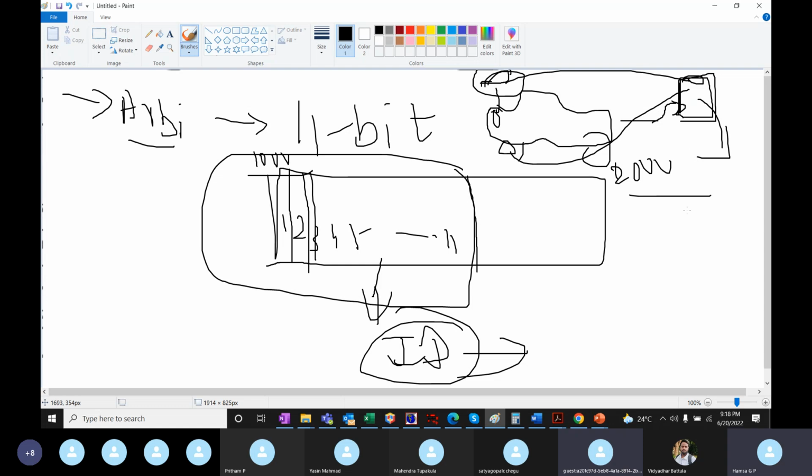Nothing but it has to send it on the bus to every ECU which is connected to the bus. So how does the ECU get to know this information is from the front camera, this information is from the back camera, or another is from the side camera? How exactly does it get to know? With the identifiers. Very good.